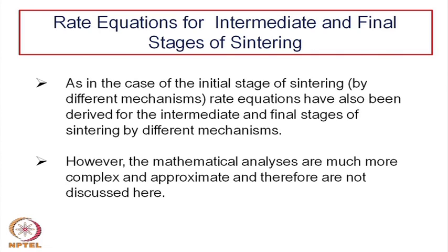As in the case of the initial stage of sintering by different mechanisms, rate equations have also been derived for the intermediate and the final stage of sintering by different mechanisms. However, the mathematical analyses are much more complex and more approximate. The exact mathematical analysis is still not available and therefore, we are not discussing it under this course.